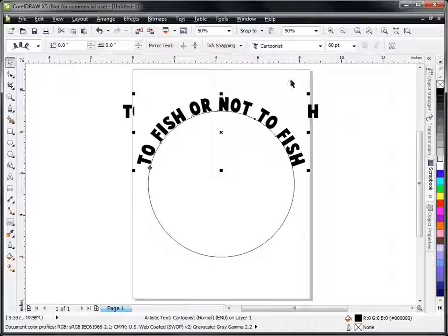You also can see that we have some garbage up here, and this is a byproduct of this tool, and it's really easy to get rid of. Just come over to your scroll bar and double click, and it'll redraw the screen and get rid of any garbage you might have on there. And that will work anytime you end up with what looks like ghosting on the screen or some character that's not supposed to be there. You can just double click and it'll redraw it.